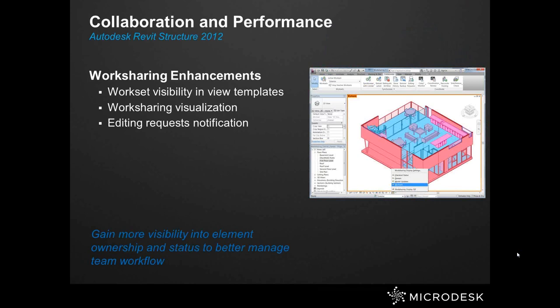With the Revit Structure 2012 release, Revit Structure increases efficiency using worksharing. The new worksharing enhancements enable you to better communicate and visualize the status of the worksharing project. Workset visibility can now be managed via view templates. This new functionality is available in the standard View Templates dialog.